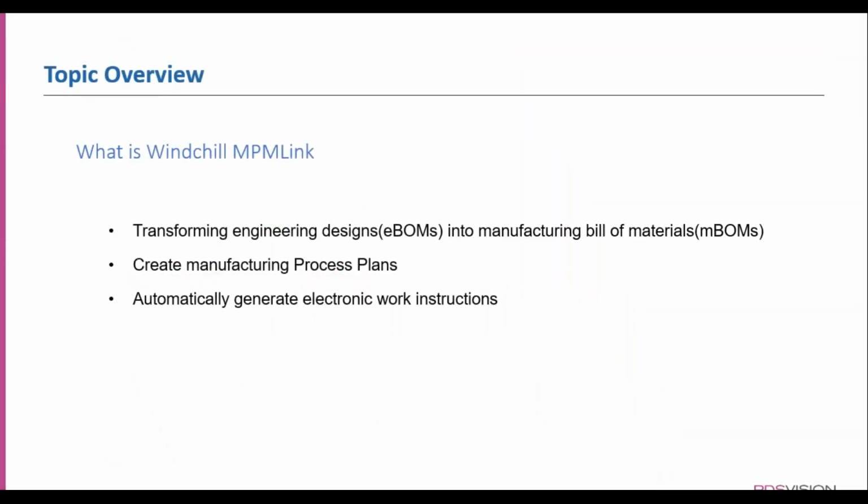So let's come to our topic. Today we have a webinar on PTC Windchill's MPMLink module. So what is the PTC Windchill MPMLink module? This module gives us a feature of transforming our e-bill of material, that means our design BOM, which is generated from our CAD inside Windchill, to its equivalent manufacturing bill of material, which will be our mBOM that we will be referring to in this webinar.